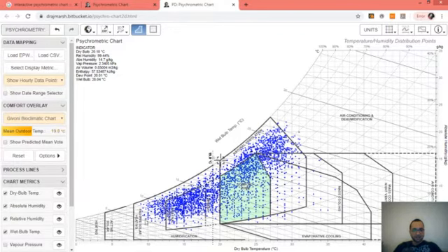We can see that passive solar heating is enough in order to meet comfort conditions. For active solar and mechanical heating, there are no hourly climate conditions that fall in this area. Most of the hourly values are within the passive solar heating. The comfort zone also has a consistent number of hours. Natural ventilation in summer as well could be used to achieve comfort conditions.